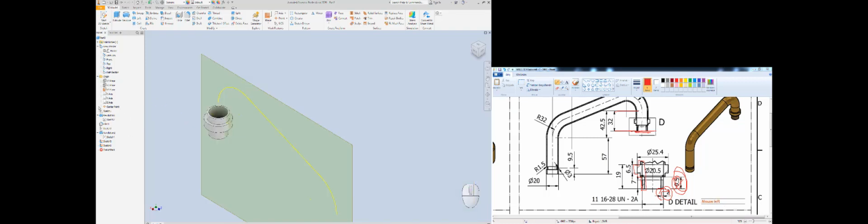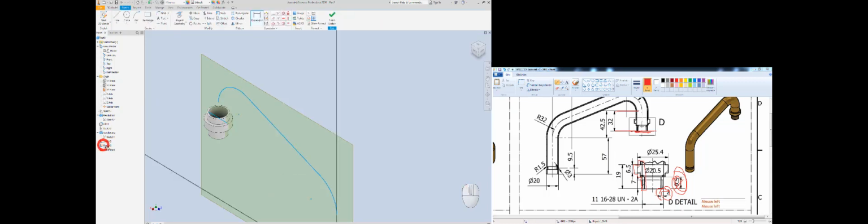We have the lines starting from these points. We will make these points, that's all. From this point, I will go to the profile section, the sketch, F7 tool, all these lines. I'm not going to use these lines, so I convert the lines here to construction.